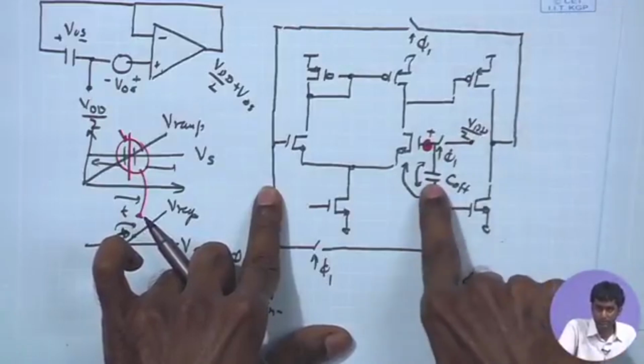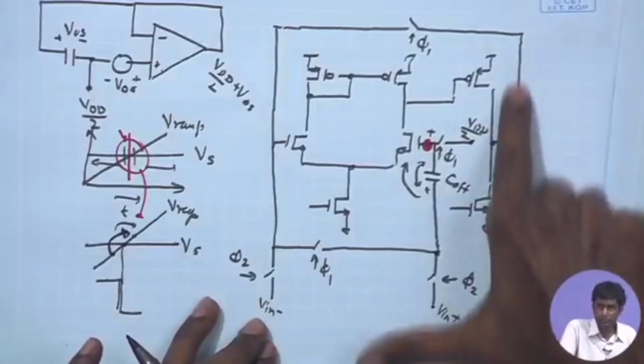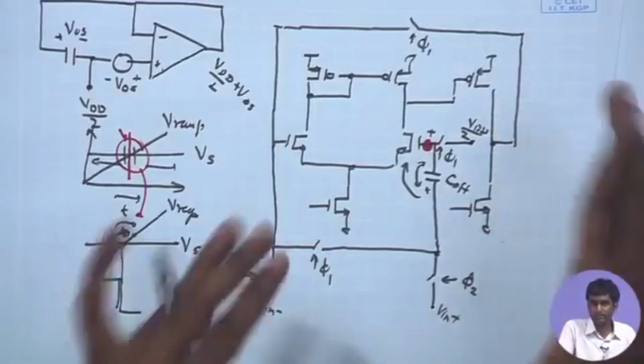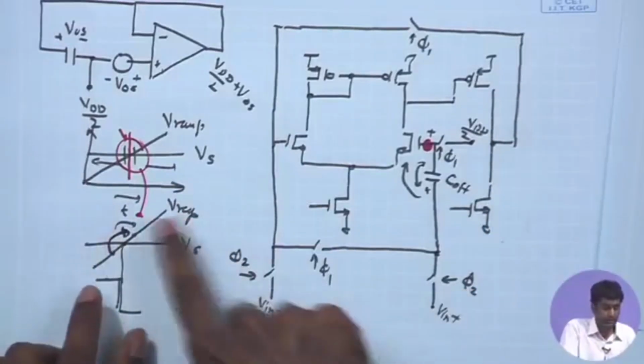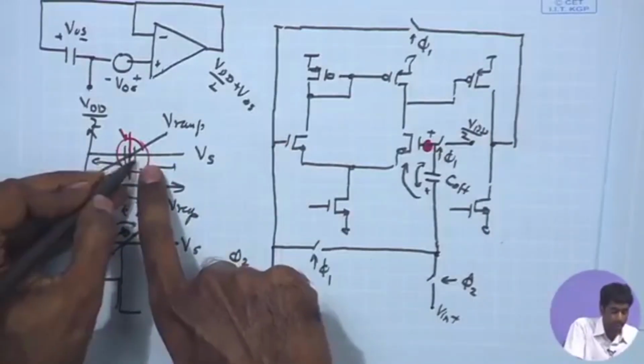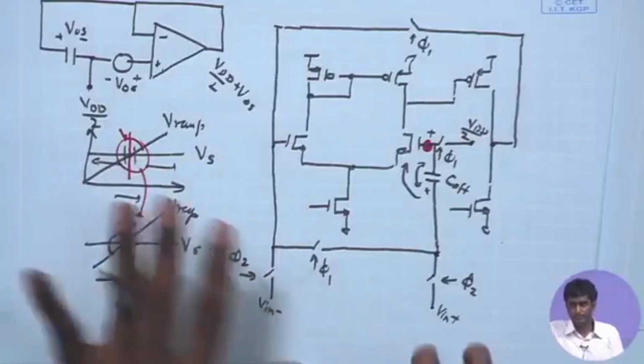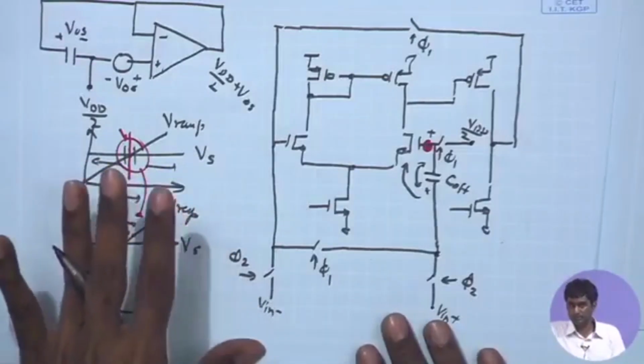So, that is already stored, that is in fact capturing the effect of uncertainty in the output point. That is in a way ensuring that the amplifier will be in high gain condition when the V ramp approaches Vs. That is another subtle point that you can think of.